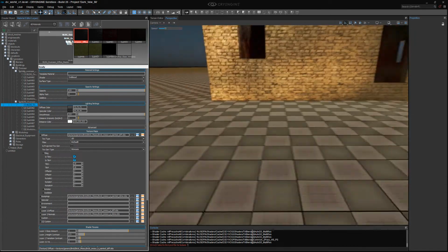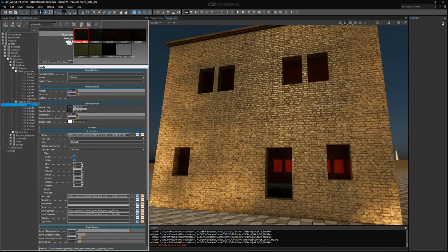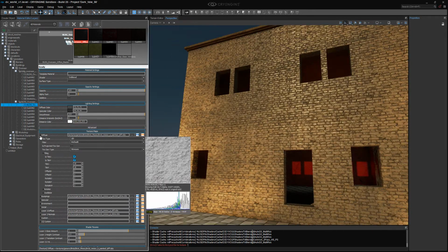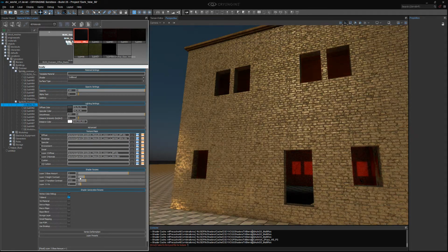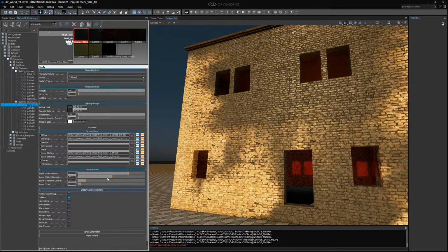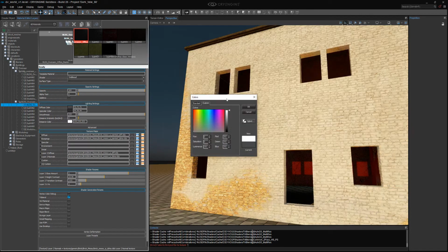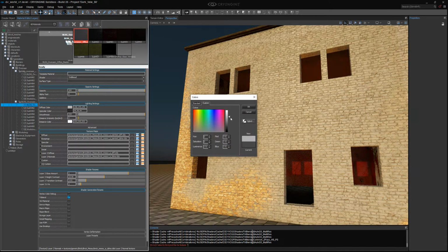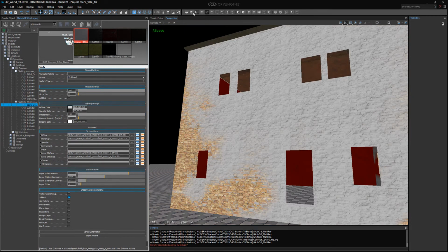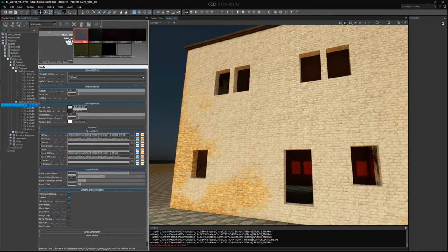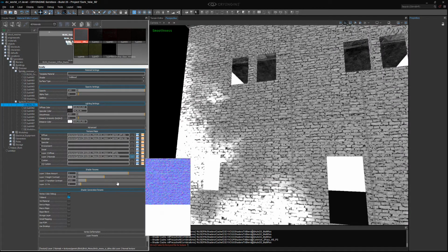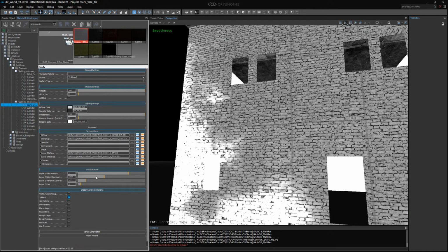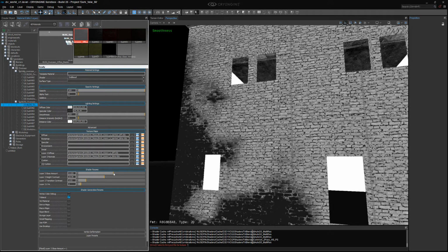Like the scale. As you can see, everything's diffused. It just took over the whole texture, but we want to make better use of our blend. So let's make some adjustments. We need to change our diffuse color to white, close to it anyway, just making sure we're not overblowing things. Alright, so real quick, let's take a look at the glossiness. As you can see, the glossiness is way too high here, so I'm going to take this glossiness amount and bring it down.